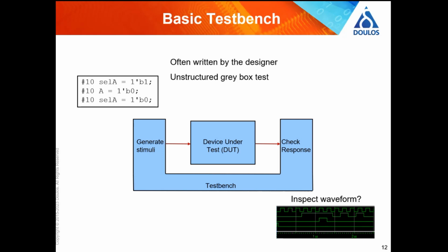You obviously need to then be checking that your design is doing the right thing. You could just look at waves in a waveform viewer, but that's pretty dumb, really. Might be okay for just checking your design is sensible, but it certainly isn't okay for verifying your design really is correct. Your test bench needs to be checking the outputs of your design under test, because looking at waveforms is error-prone, tedious, time-consuming, not repeatable. Whereas if your code in your test bench is checking the outputs, you can review that code. Once you're happy with it, you're confident that it's working, and so on.